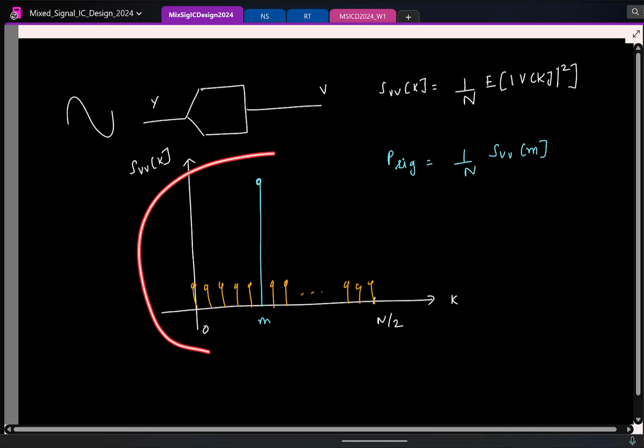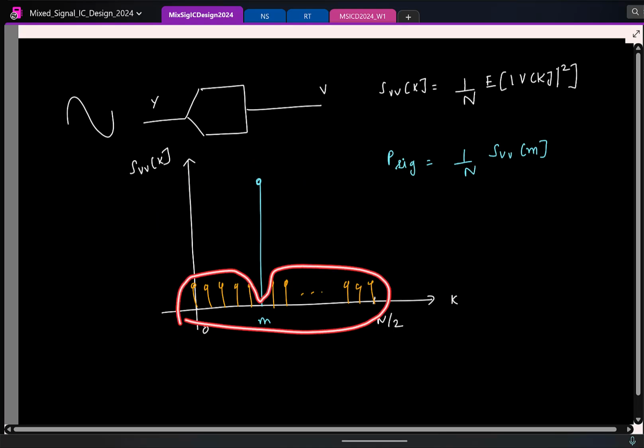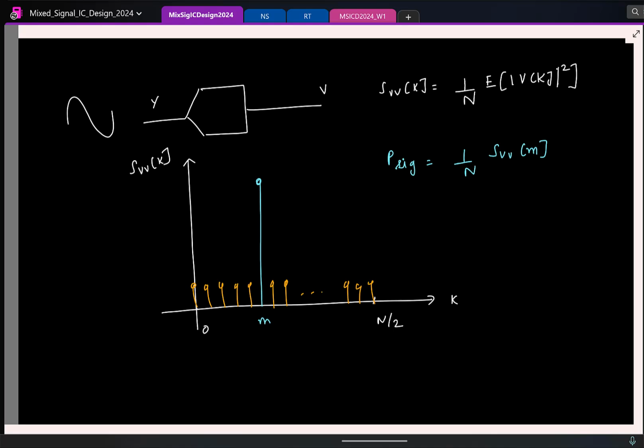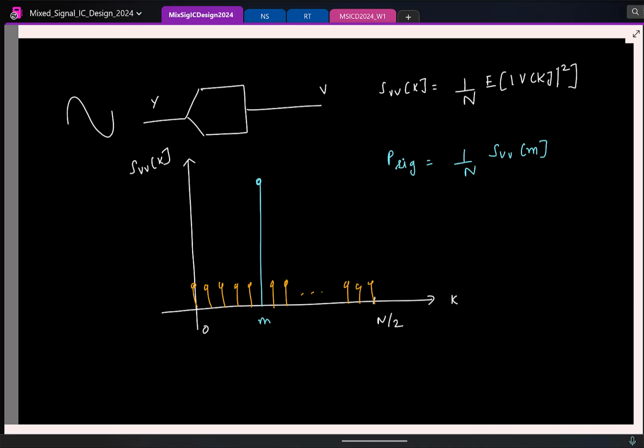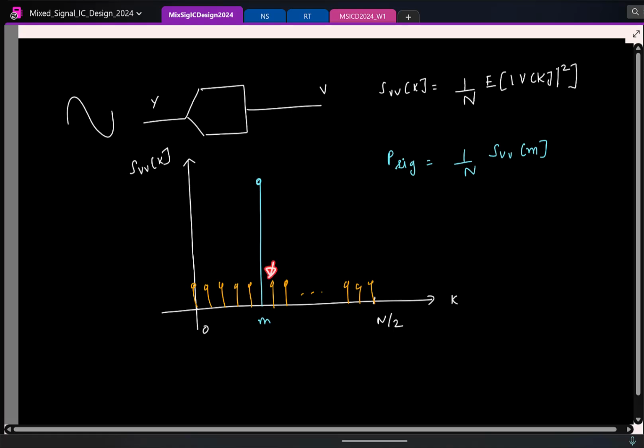Yeah, I mean, one thing is you take the total sum, subtract the thing. That basically is the same thing as saying I am summing up all these guys except this, right? Again, see, in principle, even quantization noise also occupies the mth bin, but here the signal is dominating that bin, so you don't consider it. So strictly speaking, it is not accurate, but as long as you have large enough n, just excluding one bin here will not make a difference.